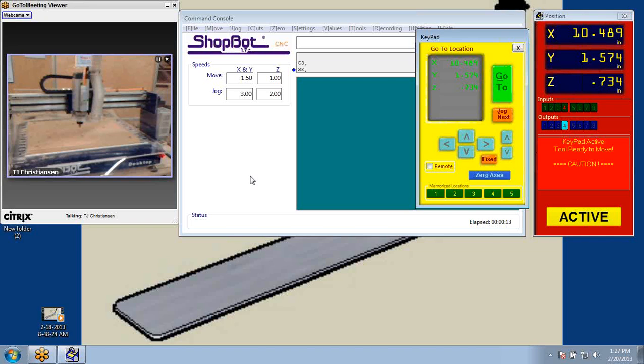So also notice there's fixed. If you click on fixed, you can change this number, so every time that you move, it moves just that amount. Right now, what if I change it to 1 inch? Every time I hit that, it moves over 1 inch. So it all depends on how you have that set. I usually leave it at about 0.01, because that way when I'm doing real small little measurements to get the Z just right, that's where the 0.01 comes in nice.